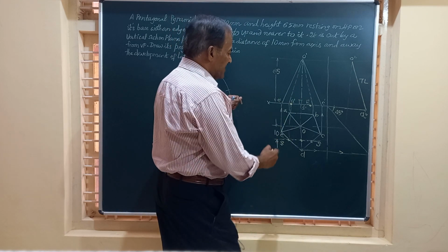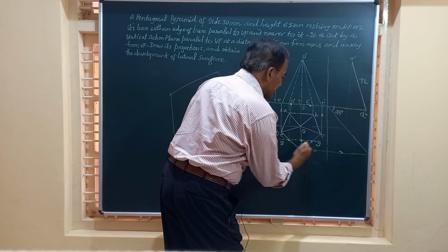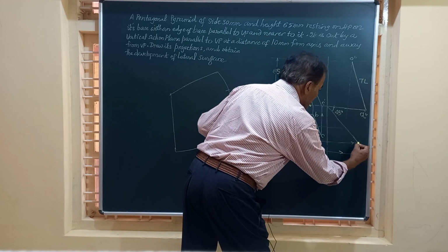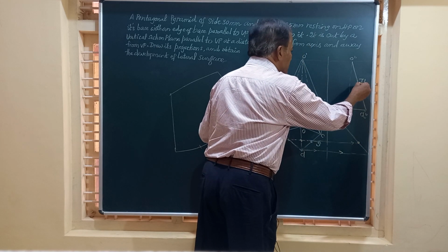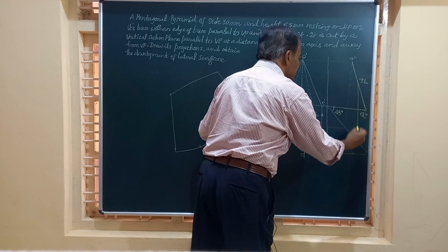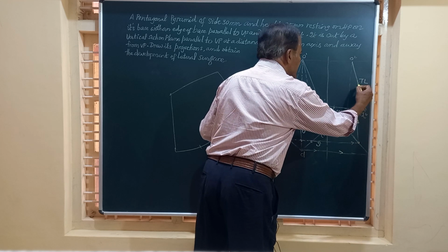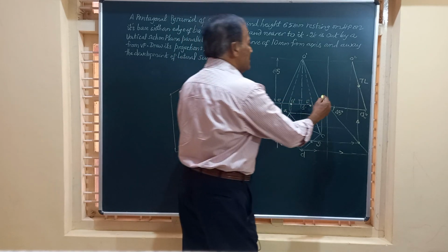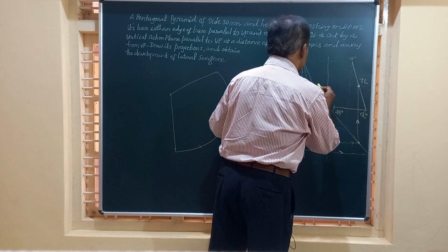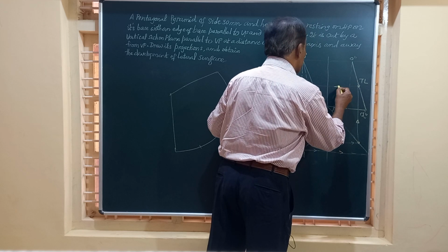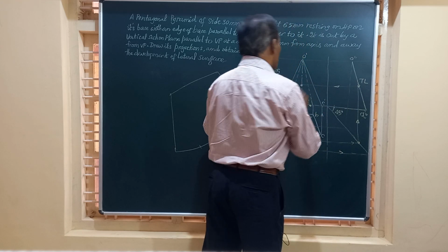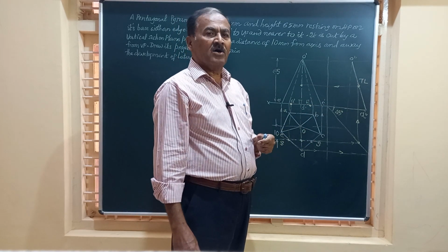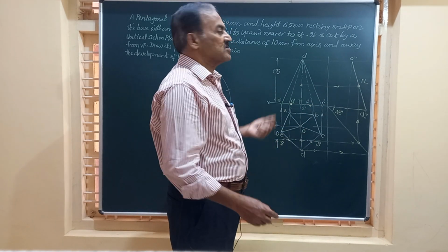How to obtain that, friend? It is cut here. OD is cut here. We have shifted that on OD to the 45-degree line. From there, draw a vertical line upwards to cut O double dash, D double dash at this point. From there, friend, draw a horizontal line like this. And you are going to get this point on OD. So this is a very nice problem. Without this concept of the true length, you cannot solve this problem at all.